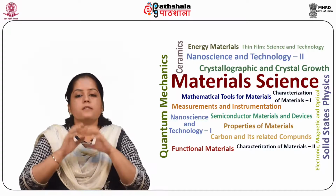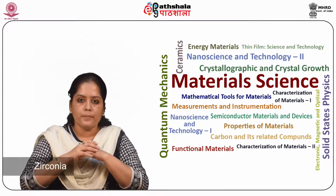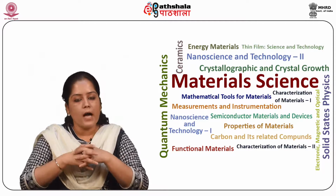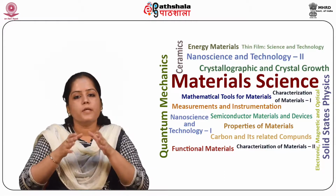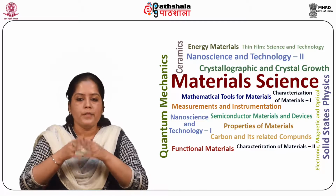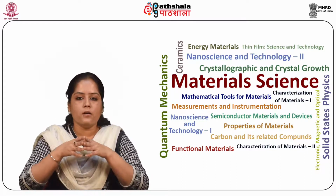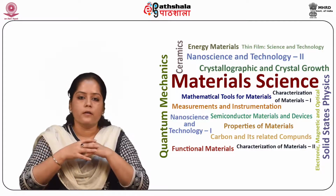Transformation toughening is the most pronounced and most well studied in zirconia. The stable phase in zirconia is monoclinic at room temperature. However, the high temperature tetragonal phase can be stabilized at room temperature if the particle size is less than a critical size. Second, a stabilizing additive like Y2O3 has been alloyed with ZrO2. So the critical size is increased by alloying.